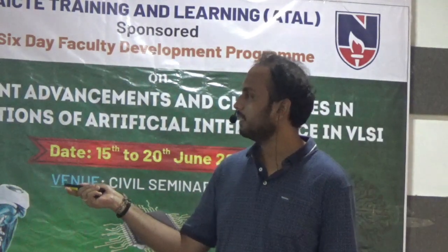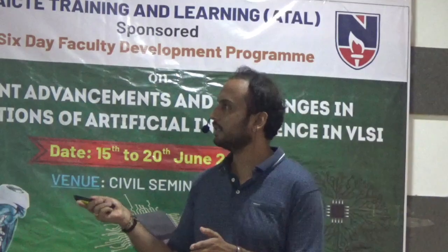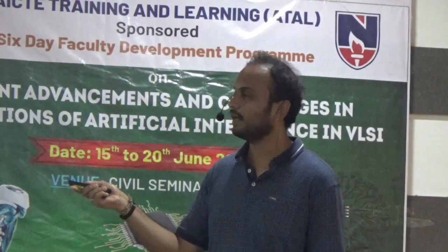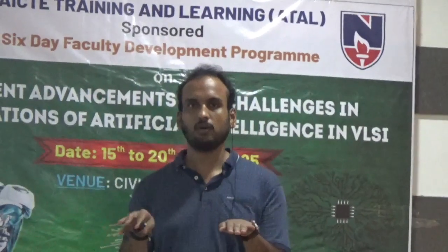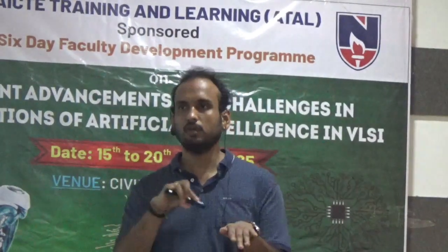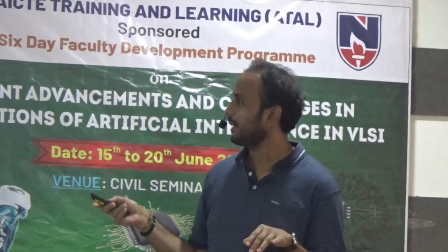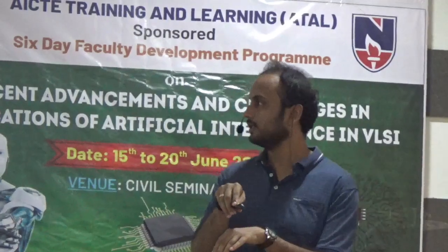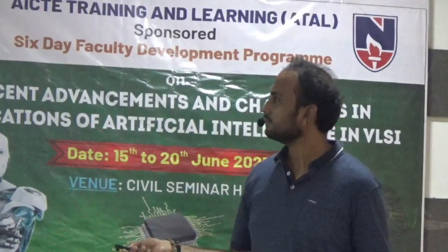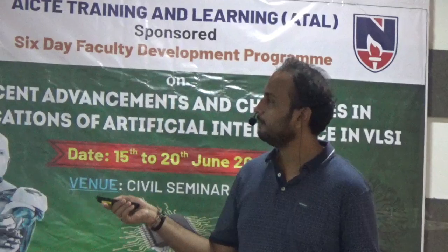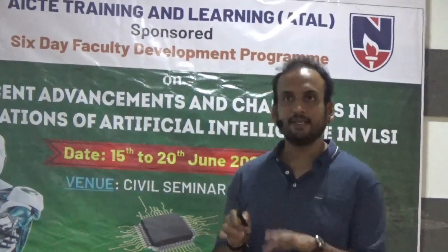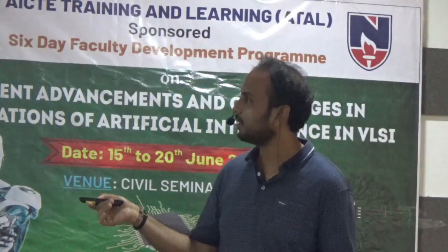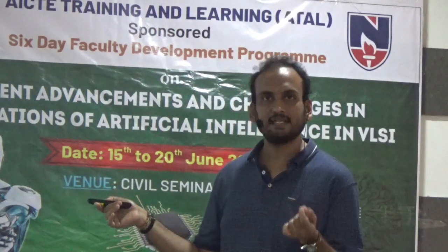People have demonstrated 100 nanometer pitch for the interconnect. These are the different schemes we use. For example, this is a 2.5D, where there are two dies on the same plane, and we use wire bond. This is called 2.5D packaging. And then we have 3D, where you put one die on top of the other. That is called 3D. So these are the different packaging and different types of interconnects which we use, and these are the different timelines, showing how the interconnect sizes are reducing.